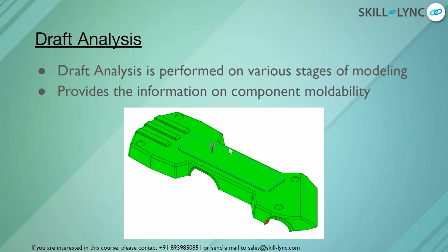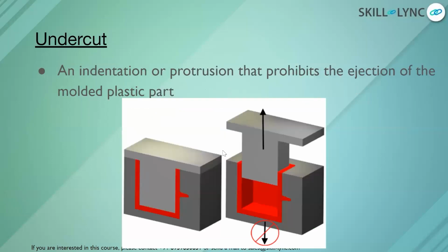Any plastic design engineer, when provided with a surface for developing a plastic component out of it, generally performs a draft analysis for the class A surface as well as finally after creating the plastic component. These are some of the requirements, or the step-by-step process they are going to perform, the first step being performing a draft analysis, right?